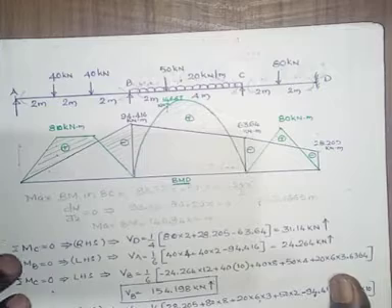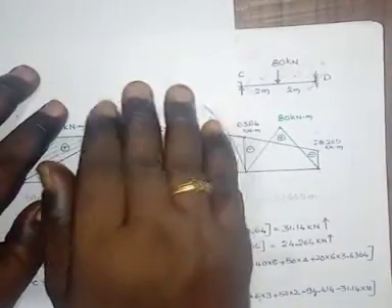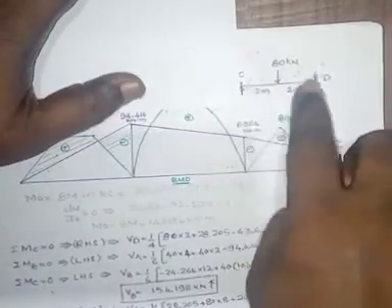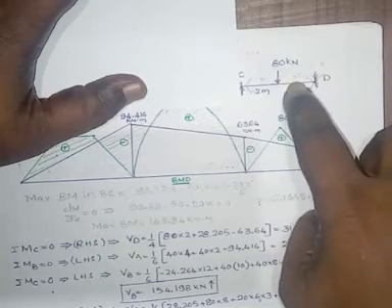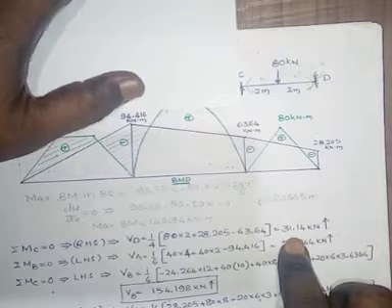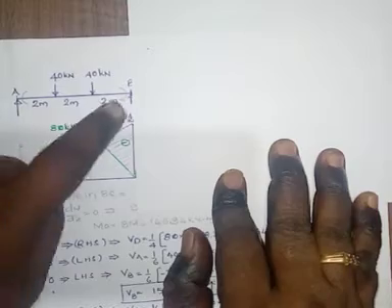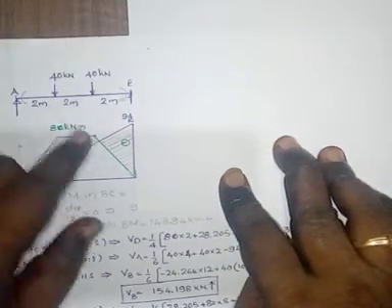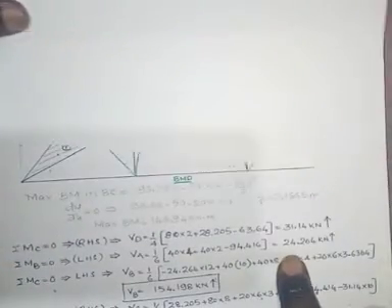Now we want to draw the shear force diagram by considering the moments of all the forces about, by considering only the right part, that is VD into 4. Then this moment to this one, moment to this one, here we will get 31.14. Similarly, summation of MB equals 0, that is LHS. Only you have to consider this is 0, this one is 94.416. Then here we will get VA, that one is 24.264.